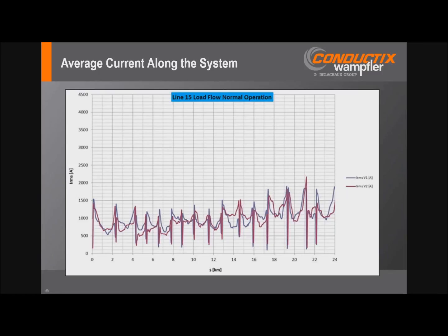Now in the U.S., the code says 3/8 inch over the surface, 1/2 inch through the air at 600 volts. So we would need 12.5, 13 millimeters of clearance to meet code. Now realistically, given construction tolerances of 6 to 8 millimeters, I would say that's not adequate. So you have a couple of things here that you would need to look at to determine that. But I would say a safe rule of thumb, I would want that at least 50 millimeters away from the concrete.